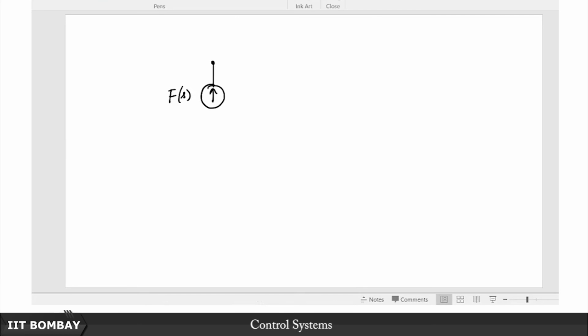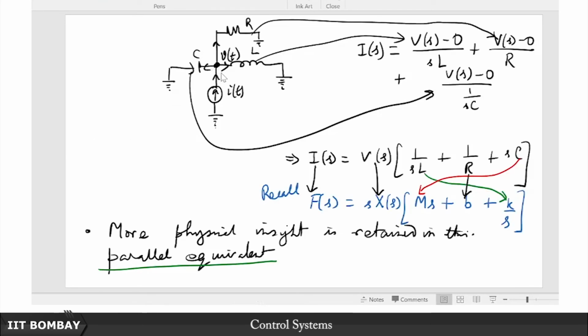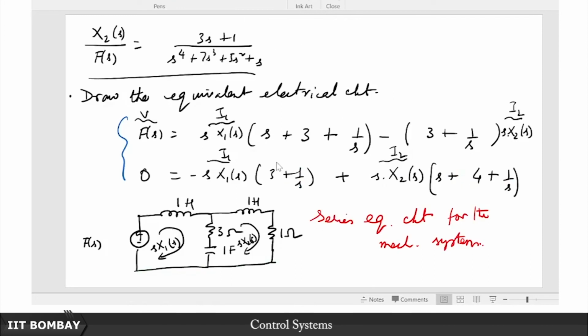Now where does this current go? It goes into parallel branches, it is balanced, right? That is what KCL is, like we had here, this should be balanced. So how do we see the KCL equivalent of this system of equations? You see now the analogues have changed. This is now the current, this is now my voltage, and these, instead of being impedances, are now admittances. So what is the coefficient of voltage 1 in the node equation for V1?